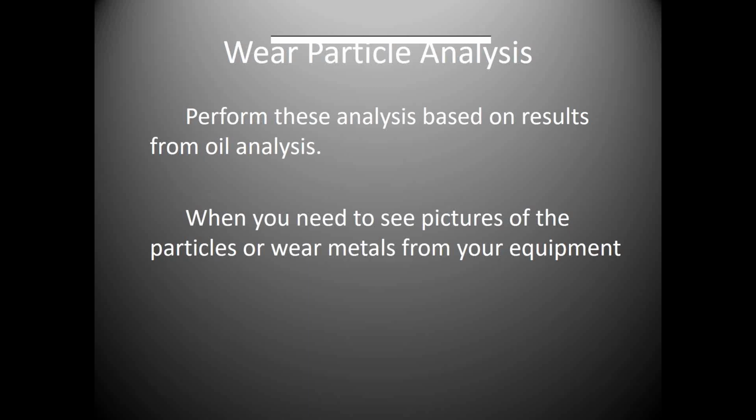They sell little concave slides. You can put drops of oil from your equipment in there and see these exact same things. And you don't have to do very many of those to pay for it. You can take a picture on the microscope, put it on an SD card, put it on your laptop, and show people what they look like. It's a good learning experience for your maintenance people and a very cheap tool.